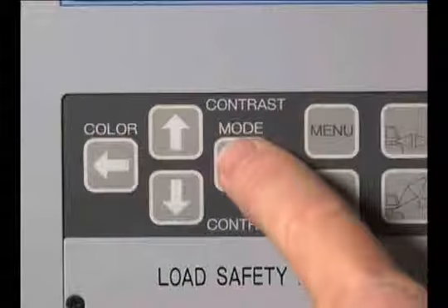The boom angle indicates the present boom angle and will instantly change as the boom function is operated. The point elevation display gives the operator the current point height from the ground. The word main is an indication to the operator that the screen is set to the main hook or auxiliary hook. Press the mode button and hold it for 3 seconds to change hook status from main to auxiliary. The load ratio is indicated here from 0 to 100%.